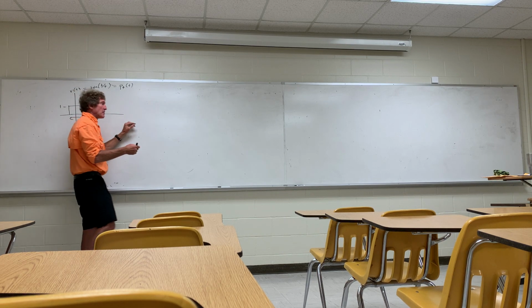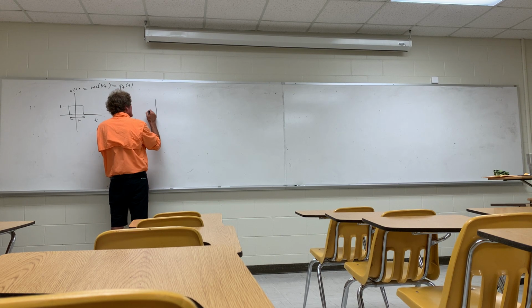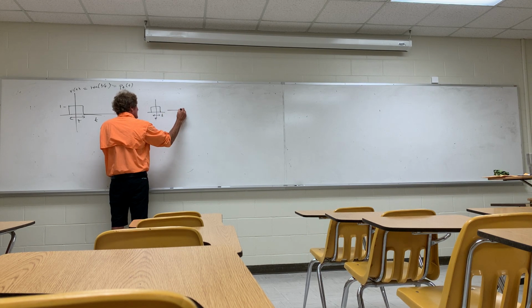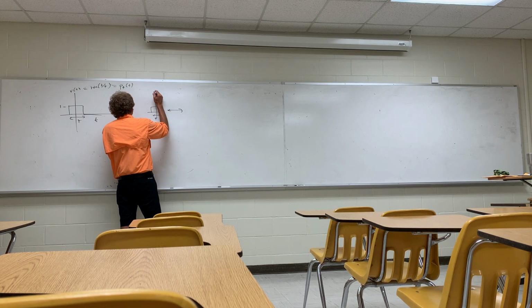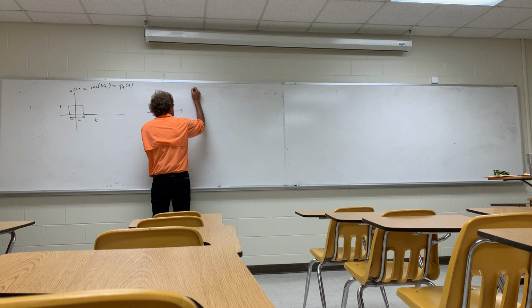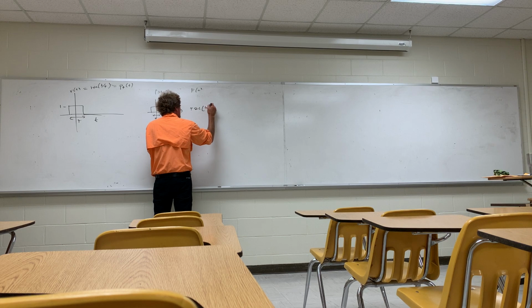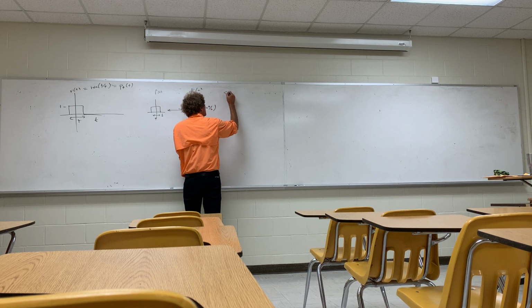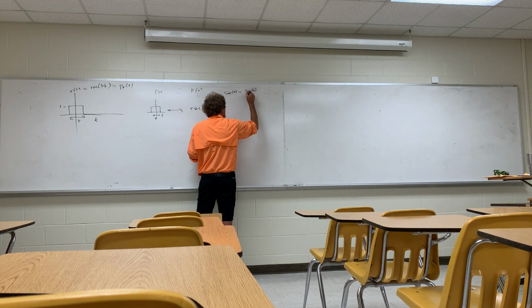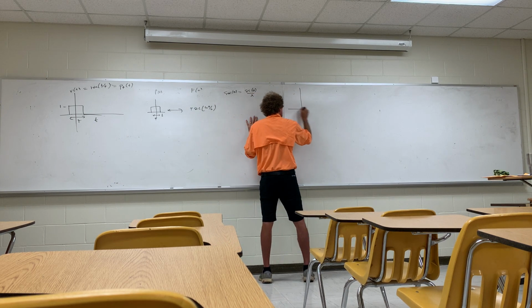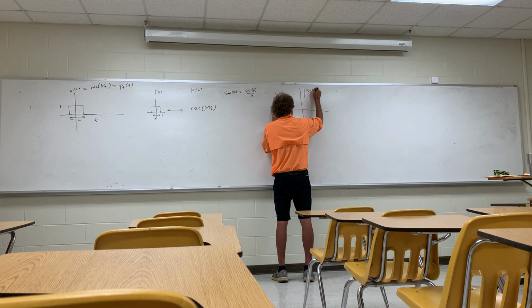So when I have a pulse function, or a function that looks like this, of width tau in the time domain, this is going to be my time domain function, f of t, it goes to a frequency domain, F of omega, of simply tau times the sinc of omega tau over 2. And the sinc function, sinc of x, is really sine of x over x. And that looks like this. If you plotted the magnitude of sine of x over x versus x, it does this.